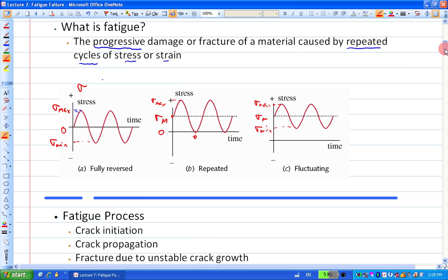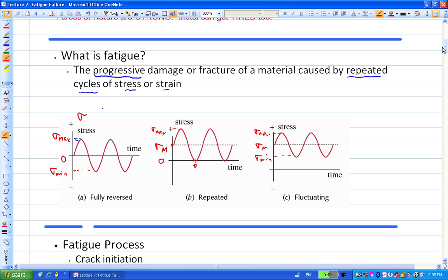What's more important for you to realize is that fatigue loading is different from static loading. How different is it? With static loading, you can see the problem before the bad thing happens. When you're subject to static loading, you see, oh look, it's yielding, it has permanent deformation. So you immediately know you're probably not going to use the part anymore. But with fatigue loading, the tricky thing is that it happens suddenly. It doesn't show any signs before it happens.